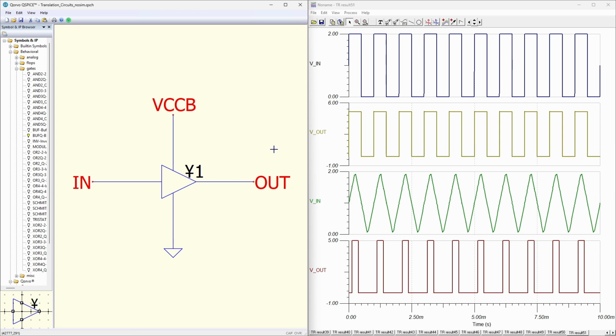Now I know this looks exactly like the other CMOS buffer that we were just talking about, but thinking about the input thresholds, these are different from the original device we had discussed. So with a normal CMOS input, the threshold is about half VCC. But this is a TTL compatible device, so the input threshold is actually closer to 1.5 volts. You can see in the simulation results that my input is a 2 volt signal, but my output is a 5 volt signal. And on the triangle wave, we can see where that's actually switching. So the input goes from low to high right around 1.5 volts.